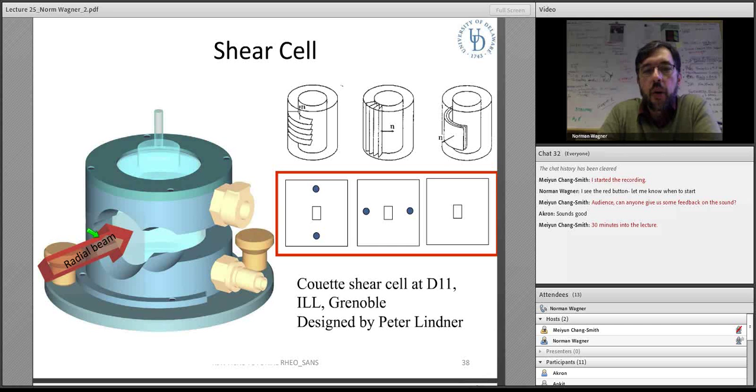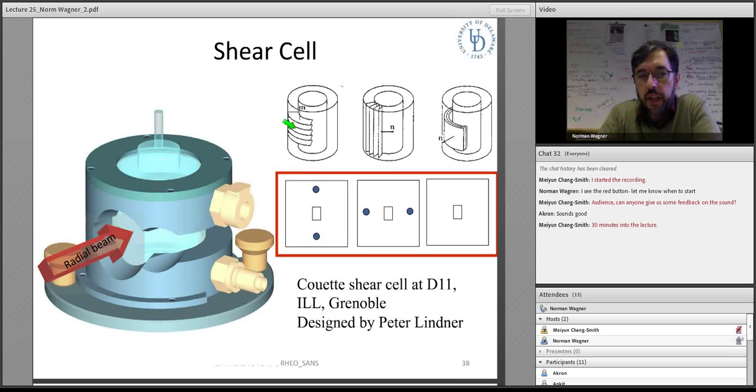And if we had oriented lamellar in this direction, by now you should recognize that that periodicity that you see here along the vertical axis would correspond to these Bragg peaks. If I had orientation in this direction, which is possible, not likely, but possible, then I would see these patterns, these Bragg peaks.